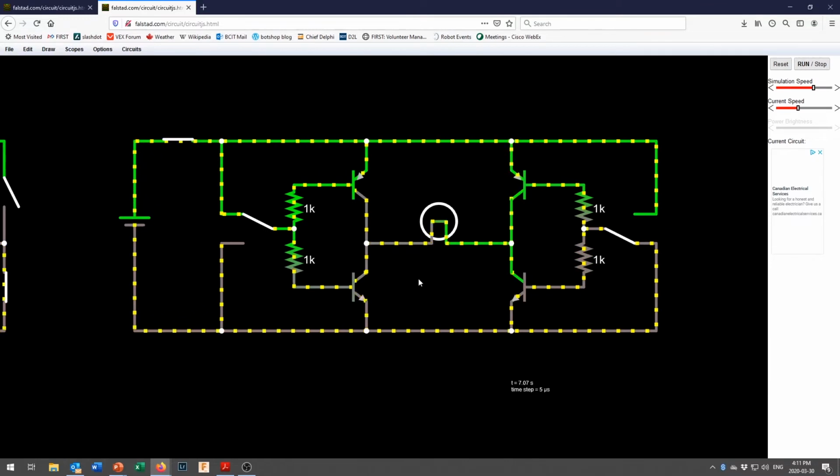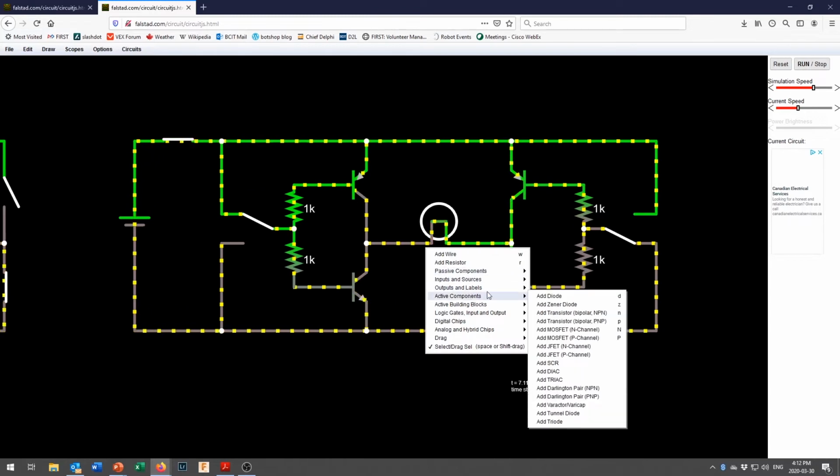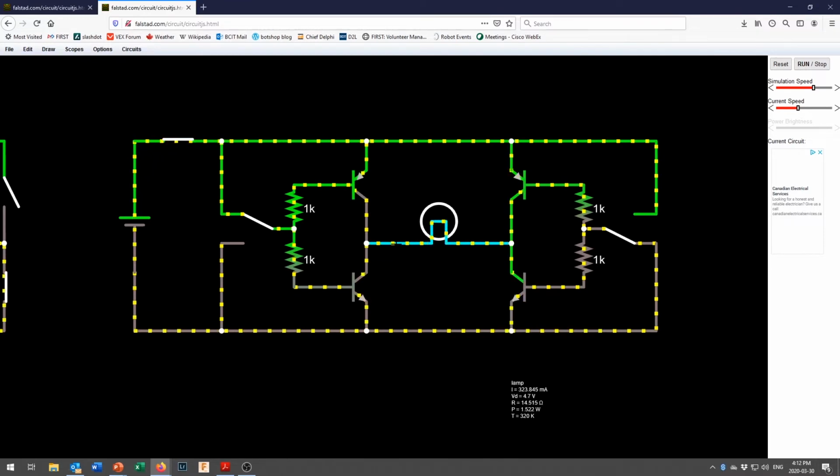So what we'll sometimes do to help protect against that is we will add some diodes, these things called protection diodes that will come in right here. Now, if we add that right there, then the electricity is just going to go straight down to the ground. What we do is we put it up that way. And you'll say, well, why would you do that? Because electricity will never flow through this way because the voltage up here is always higher than the voltage down there. Well, I don't want that. I want it going the other way.